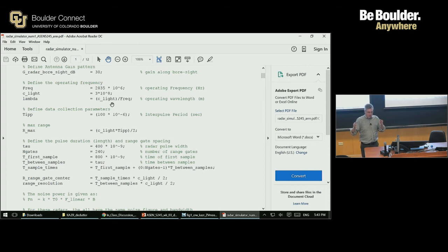If we change the operating frequency to a longer wavelength, lower frequency, then the target could move more before we've moved so much of a wavelength, so much of a phase. We'll get into those details, and you wouldn't want to have to remember them, but you'd want to crunch through and be able to do the calculations of, oh, we've now moved pi over 8.